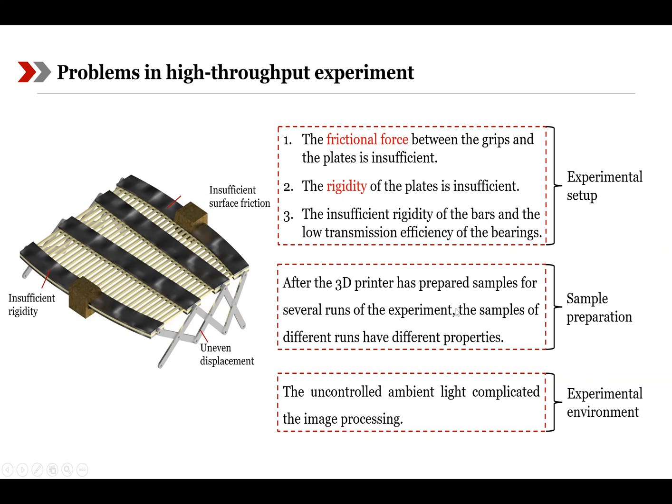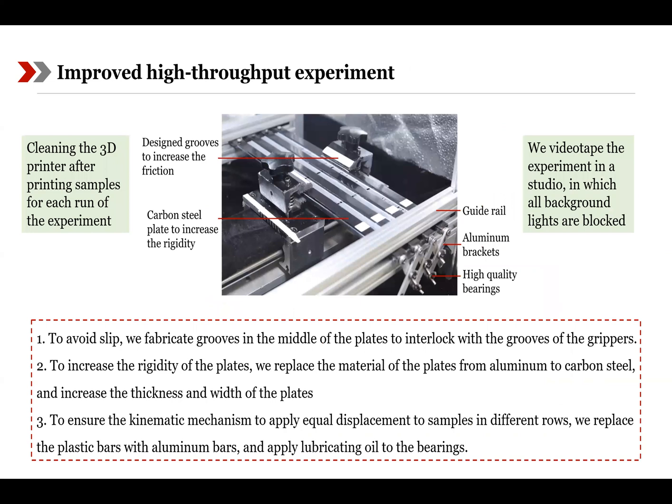processing. The previous experiment was conducted in changing light. The uncontrolled light complicated the image processing. To resolve these problems, we improved the experiments as follows. To avoid slip, we fabricated grooves in the middle of the plates to interlock with the grooves of the grippers.